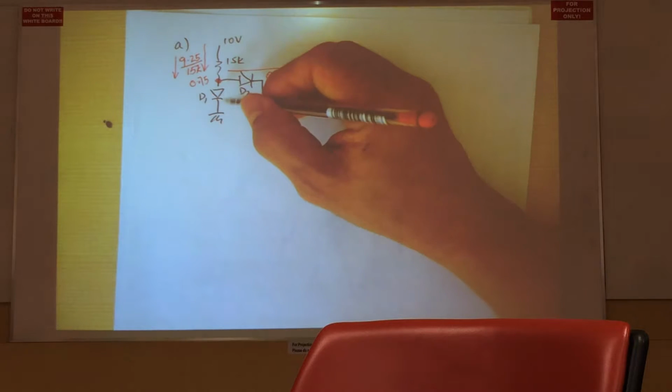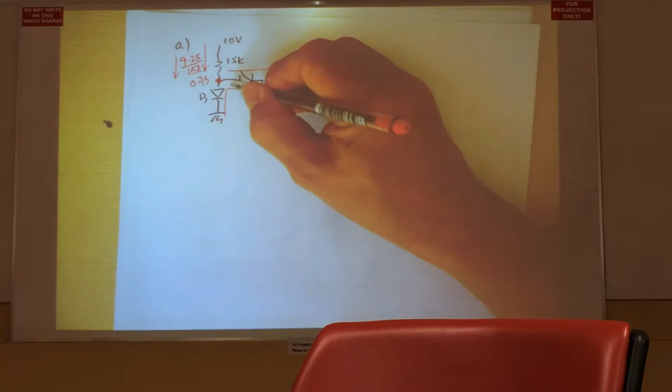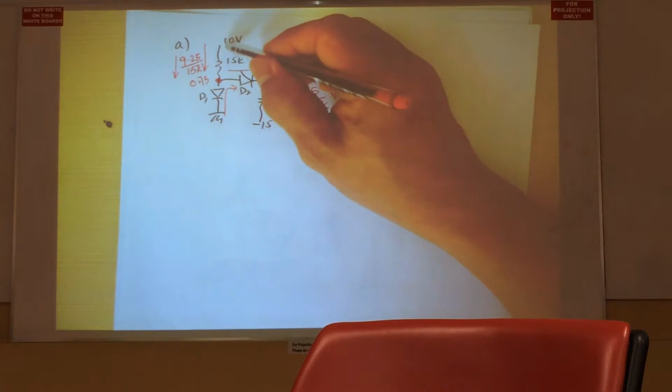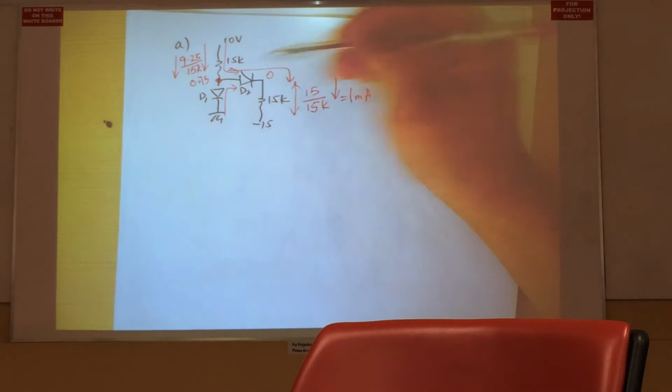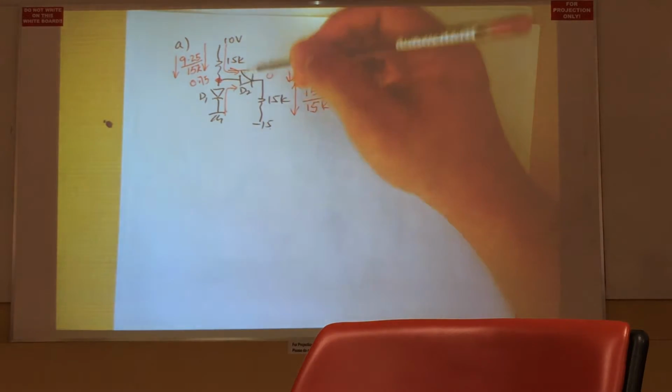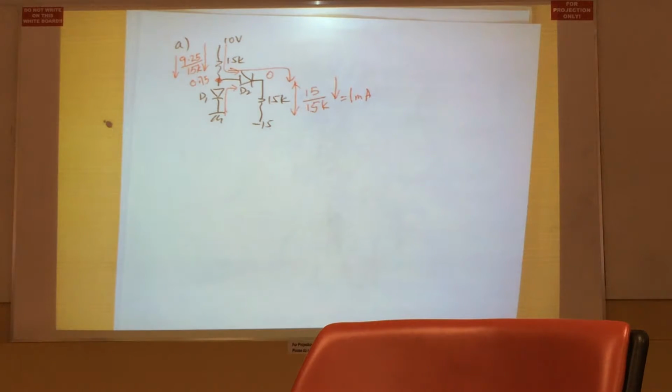So this supplement has to flow up through D1 in order to supplement the current that's flowing here. Alright? So therefore, in order for this current to flow through D1 from ground, or from the cathode to the anode, it implies that D1 would be reverse bias. Alright? So our first assumption that both are forward bias is wrong. Only D2 is forward bias and D1 is reverse bias.